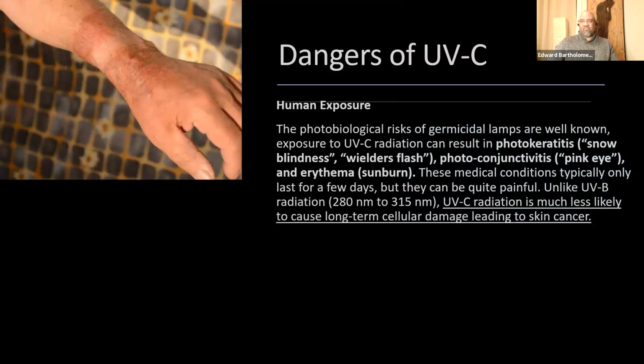There are some absolute dangers in utilizing UVC, and that's at the 254 nanometer range, and the 280 to 315 range. There are issues regarding overexposure that can be an irritant to the skin, can absolutely cause things like blindness, welder's flash, photoconjunctivitis. Things like that can happen for people who are overexposed. Anyone who's done any welding has probably dealt with this on their skin, where the arc welders will actually leave an irritation if you're exposed to it for too long. That's why you cover up in these types of situations.